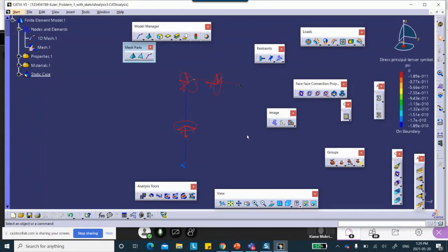Now, some other software will plot you von Mises stress, for example. But then you have to go and read the documentation: at what location did they calculate this? For example, they might say center at the neutral axis, the top fiber, or the bottom fiber, or you can even say where you want it, you input it. But don't be fooled. Do not expect to get stress distribution like before just by saying, give it to me, because you have to say where. This is why they don't have it here.